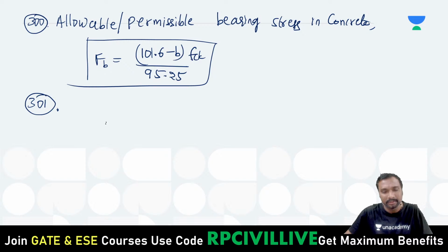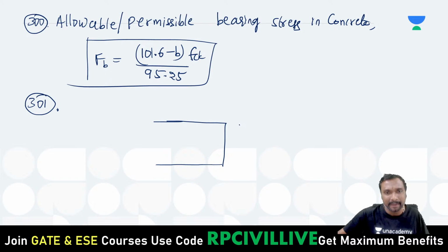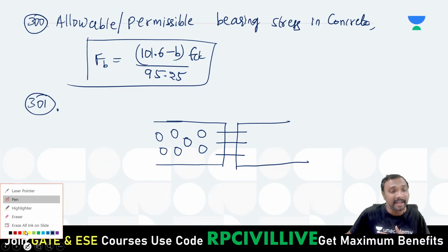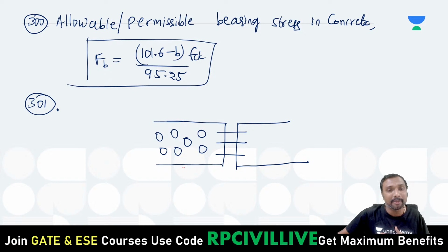What is that? You can say, if we just observe, suppose this is one panel in plan. In plan, this is another panel. These are the dowel bars you are having. Now tell me, do you give a guarantee that these dowel bars will transfer all the wheel loads present, or they will transfer the wheel loads nearby this dowel bar only? They will transfer only the loads which are nearby the dowel bar, means within a distance lesser than or equal to L. So this load will be transferred, this load will be transferred, but these loads will not be transferred.